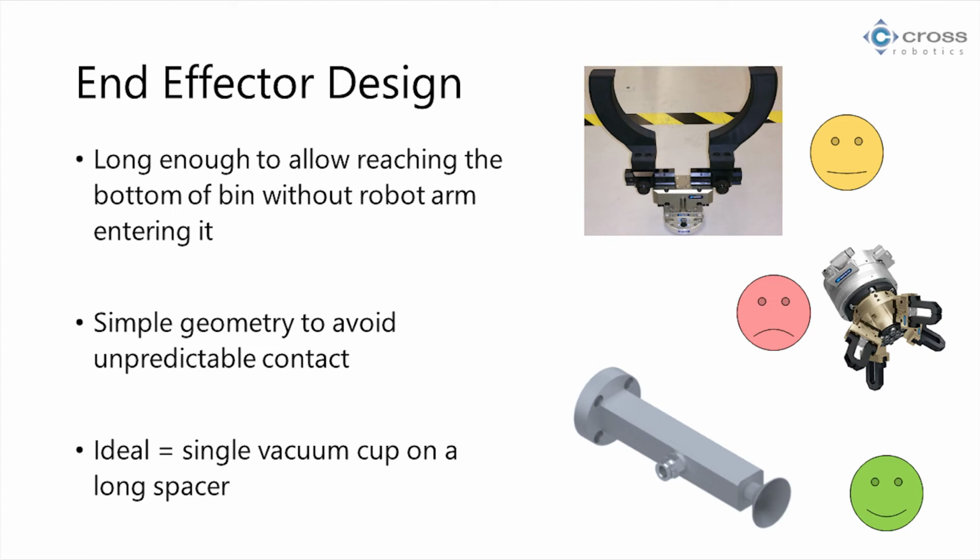So these, like I said, are for finding a part and then communicating offsets to a robot. There's not a lot of path planning that goes on, so you're not dynamically telling the robot, I need to move this way into the bin. You're telling it, this is your general approach point. Based on the location of this part, offset it here and go and pick up the part, right? So if you can avoid reaching into the bin with the actual robot, it makes your application a lot simpler.